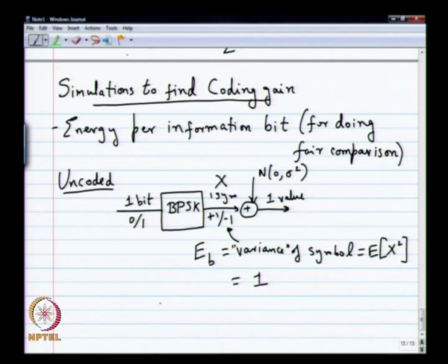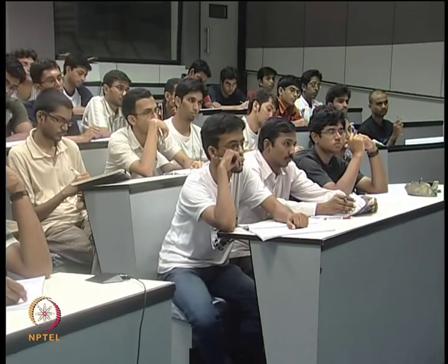All right. So now noise power, we simply take it as noise energy, so to speak. Noise energy, we simply take it as sigma squared. If you convert from white Gaussian noise through the correlator, etc., you will see this is the same as N0 by 2. This N0 is some number that communication engineers will talk about. It's the height of the noise spectrum. It depends on the temperature, etc., so you can put down some number for it.